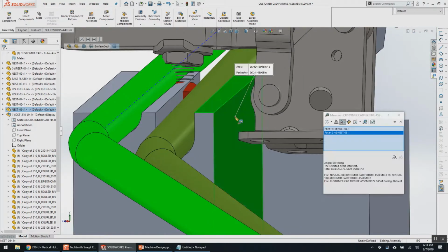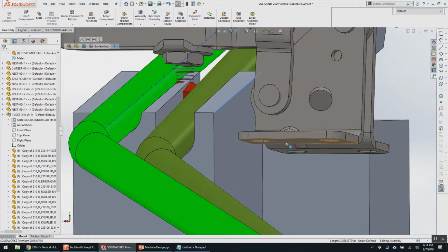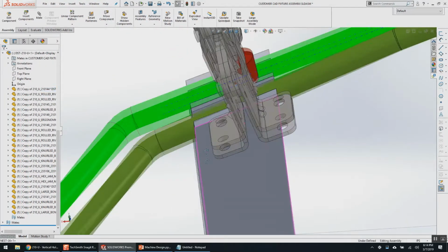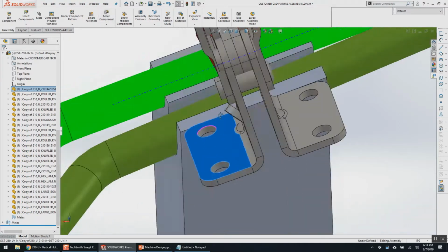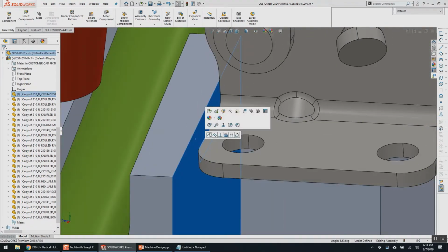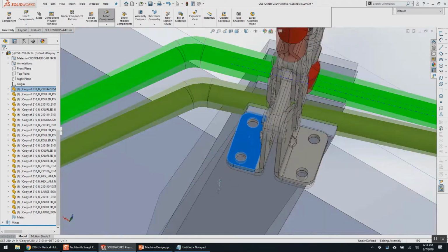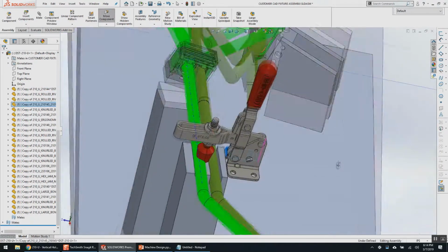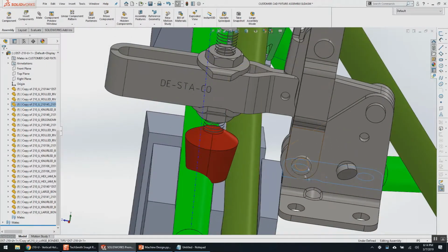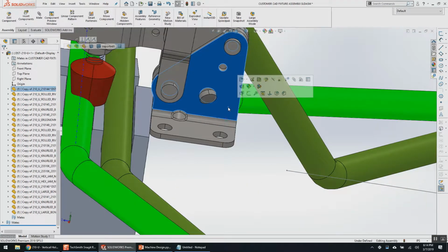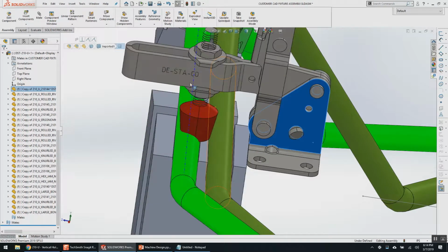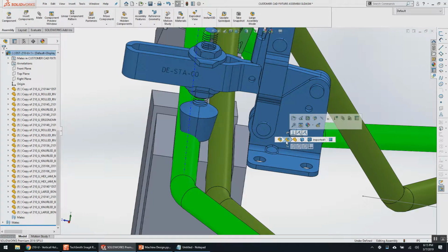So let's say we want to mate that face coincident. Okay, so that face must not be perpendicular to that side. It is not, it's 90.0 something. So we'll just pick the edge then and the bottom there as coincident and kind of sort of center that maybe. Pick this and do that as coincident. Then we'll have to pick some arbitrary size there. Looks like I will need that bumper, and it looks like that is too close. So I'm a big fan of breadcrumbs, so I need to adjust this mate so I can move it over so I can have another one of these. Maybe I can put one in the middle, we'll find out.